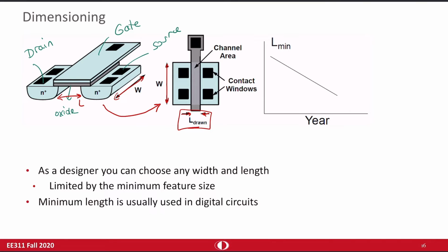Like you can make the transistor 3 micron, maybe in the 1990s. But nowadays, in the 2020s, people have 20 nanometer, even less. 1 nano is 10 to the power minus 9. 1 micro is 10 to the power minus 6. So what does this mean? As the technology improves, you can make these transistors much smaller. So what is the advantage? The first advantage is that on the same silicon area, you can fit more transistors.